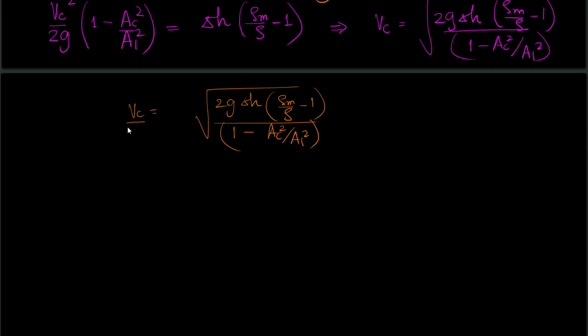In order to accommodate the various losses that may occur, such as viscous losses or eddy losses because of the flow recirculation, those losses are accounted for through a coefficient of velocity, CV, that is the actual velocity upon the theoretical velocity.